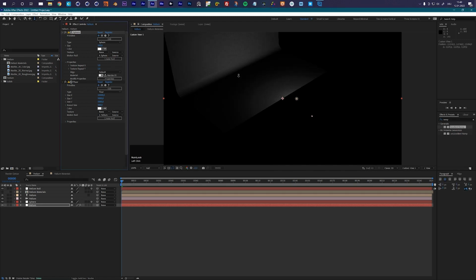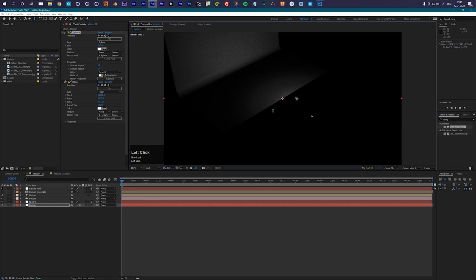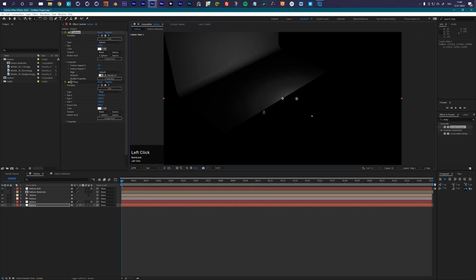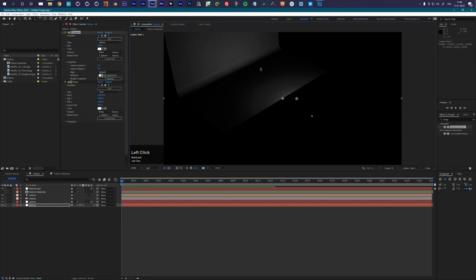Another little hint, you see that my resolution or my quality is not that good, and this is because I am actually in half resolution. If you're dealing with complex models in Helium and you have problems with the performance in your viewport, then I would recommend to just lower your resolution to half. If you are working in very high resolutions, maybe even further, but this will increase the performance in your viewport tremendously. So you see, if I go to high, then of course everything looks slick, but if I go to half, it's just a little bit of a preview quality here.